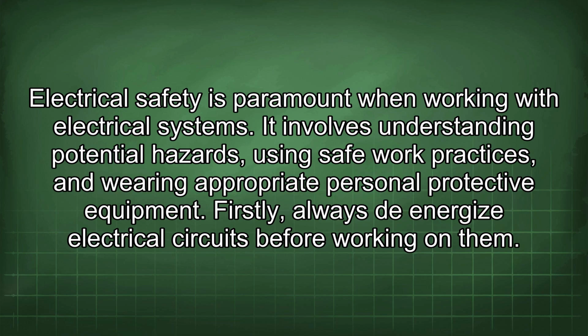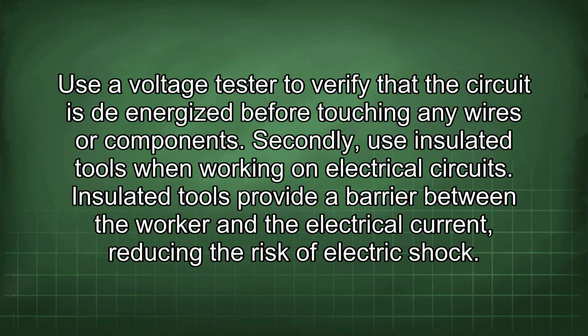Electrical safety is paramount when working with electrical systems. It involves understanding potential hazards, using safe work practices, and wearing appropriate personal protective equipment. Firstly, always de-energize electrical circuits before working on them. Use a voltage tester to verify that the circuit is de-energized before touching any wires or components.